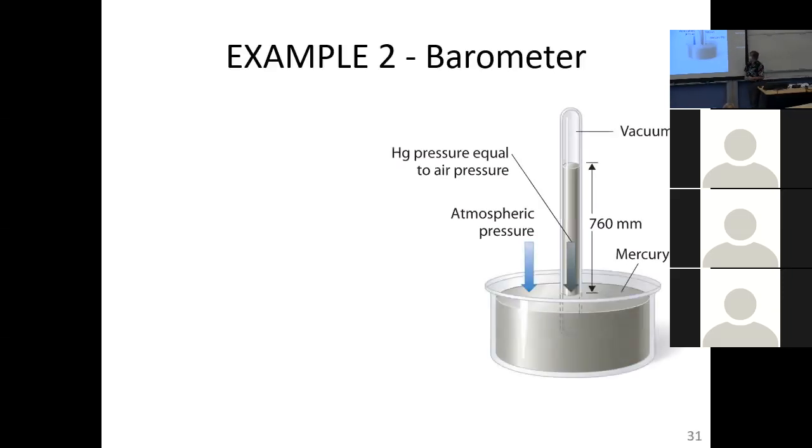Okay, here's the second example for today. Many of you, if you ever listen to the weather on either the television or on the radio, they'll talk about barometric pressure. So remember, when we talked about pressure measurement, we indicated that there are certain devices that measure absolute pressure, and other gauges that only measure gauge or local pressure. And the difference is that anything that measures gauge pressure, that gauge is zeroed on local atmospheric pressure.